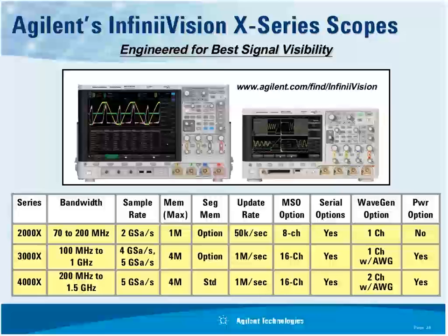Typically, 100 to 200 megahertz is going to be sufficient bandwidth. You don't need one of these bleeding edge, expensive, high-performance oscilloscopes to perform these power supply measurements. Now, you might say, my input frequency on the AC input, I think Europe is primarily 50 hertz and the U.S. is 60 hertz, so you certainly don't need a high bandwidth scope to make those measurements.